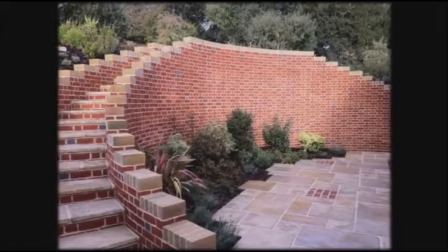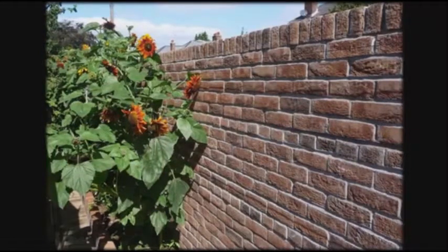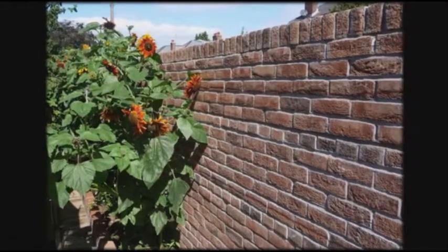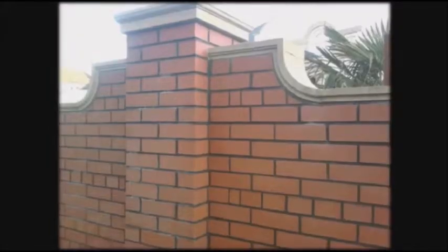Today we will learn about garden wall bond, where it is frequently used, and the types of garden wall bond. This type of bond is suitably adopted for one brick thick walls, which may act as a garden wall or a boundary wall. In garden wall bond, it is possible to build uniform faces for a wall without much labor or expense. This type of bond is not as strong as English bond, and its use is restricted to the construction of dwarf walls, or other similar types of walls, which are not subjected to large stresses.